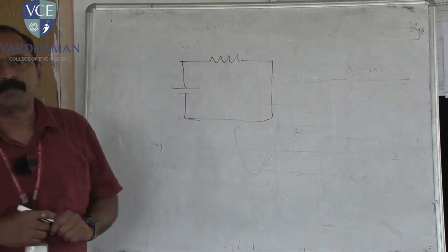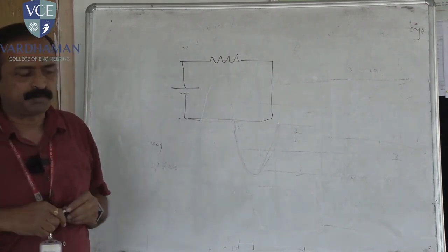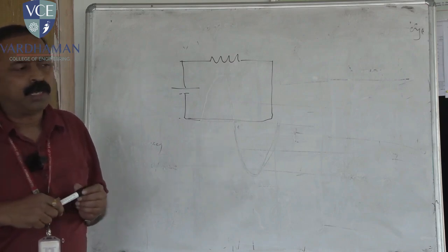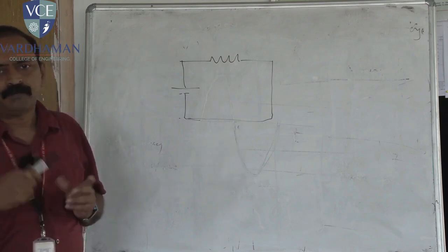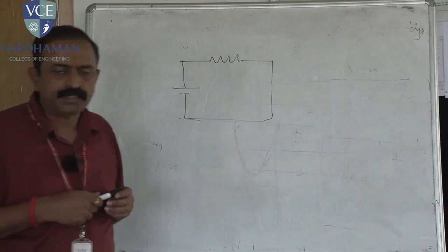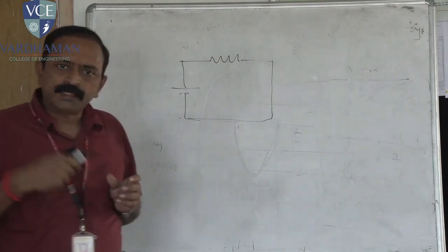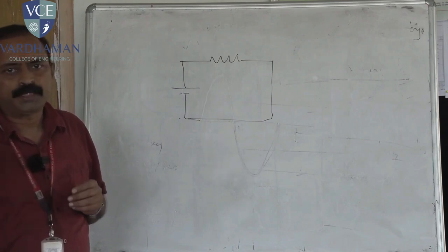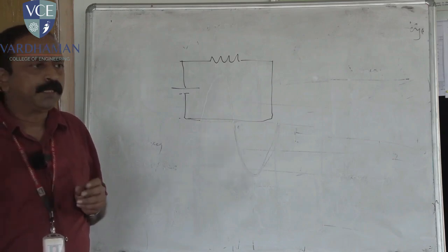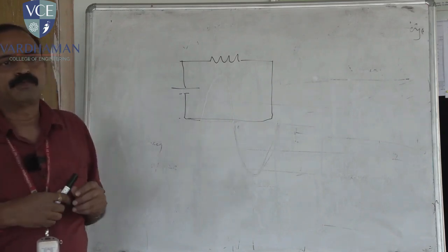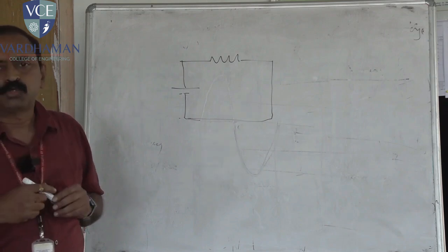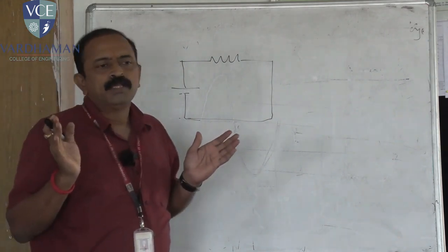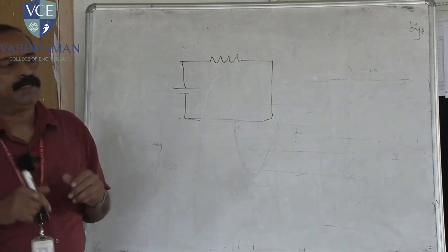These are the basic safety precautions we need to take in the BW lab experiment, because we are doing some second cycle experiments on motors on 220 volts DC. As I have already explained, DC is more dangerous than AC. It is not that AC is not dangerous. So we are doing 3-phase voltage, which is 440 volts, on an induction motor, and single phase voltage on transformers, 220 volts 50 hertz. So for the second cycle experiments, everyone should know the safety measures.